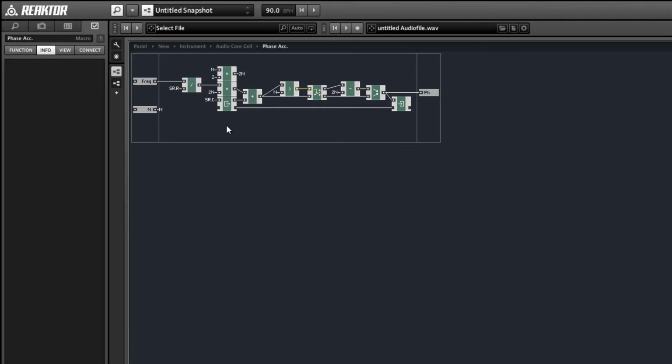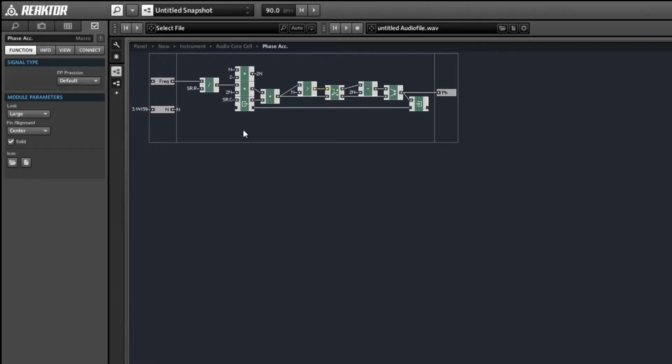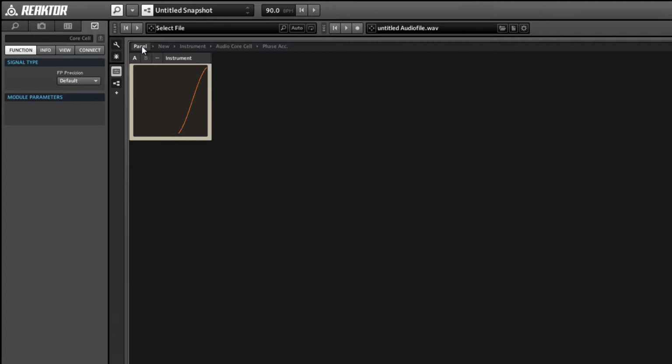And the last thing I want to mention is this cool little feature that core inputs have, where you can declare a default value, and if that input is not connected to anything in the larger structure, then the default value will be used. So I'm just going to declare a default value for n of pi because it's the most commonly used value for a phase accumulator to use. And when we jump back to the larger structure, since n is not connected to anything, it's simply going to default to pi, and we'll have the same values coming out of the phase accumulator as we did before.